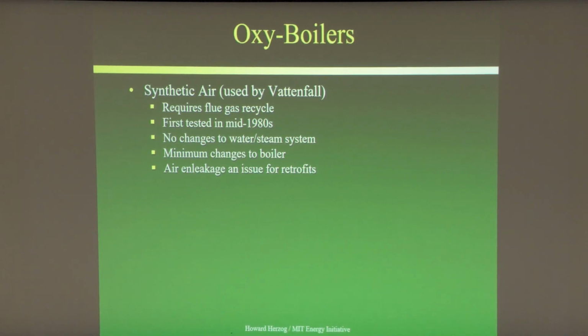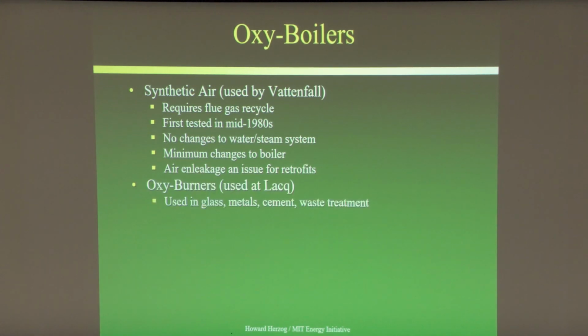If you get too much air in-leakage, you defeat the whole purpose of using basically high purity oxygen in the boiler. And sometimes a lot of these boilers work at a little negative pressure for safety reasons, and therefore there's a good chance for air in-leakage unless you really tighten up the boilers.